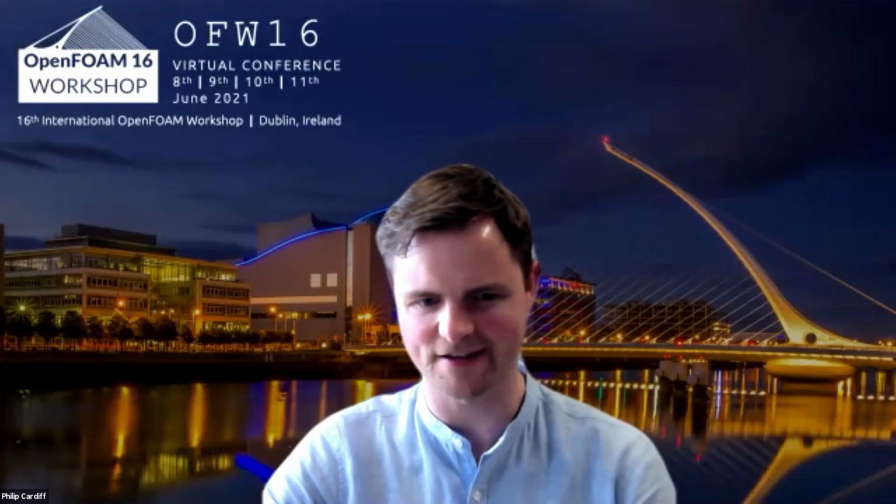Certainly could have, yes. rhoCentralFoam would give a very similar result to what you see here, except that it's an explicit code, whereas we're talking about an implicit code here. So we would have been restricted to very, very small time steps, probably even smaller than with the sonicFoam case. rhoSimpleFoam or rhoPimpleFoam, from looking at the code, is very similar to sonicFoam. I can't remember which version of OpenFOAM, maybe people in the chat can say, but I think sonicFoam was merged into rhoPimpleFoam in one of the versions, so that wouldn't surprise me. Essentially the same.